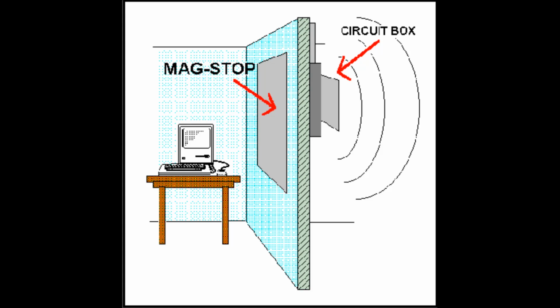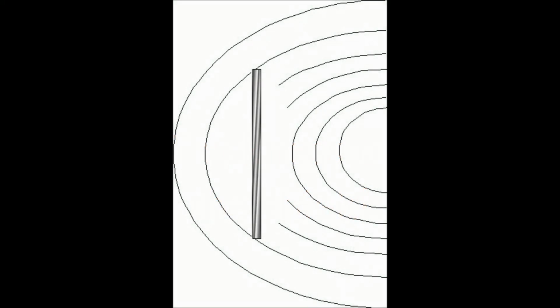If the presence of a sidewall, floor, or ceiling restricts the size of the shielding material, it can be continued around the corner, but the metal must be continuous or properly joined. Number of layers or thickness of the shield. Shield performance increases with increased thickness or number of layers. The relationship is nonlinear. Ultimately, the required thickness will depend on how much attenuation is needed and cost.